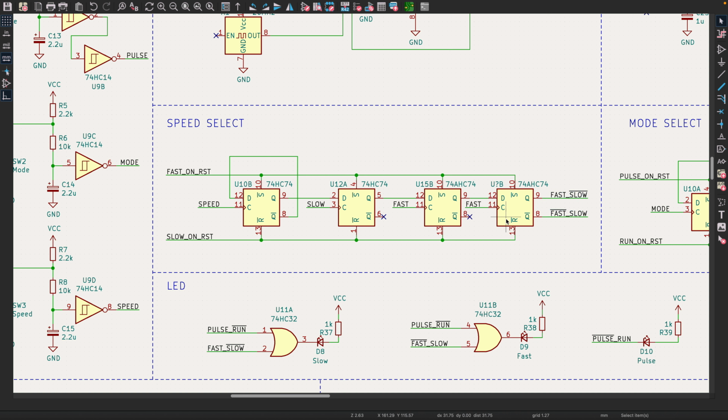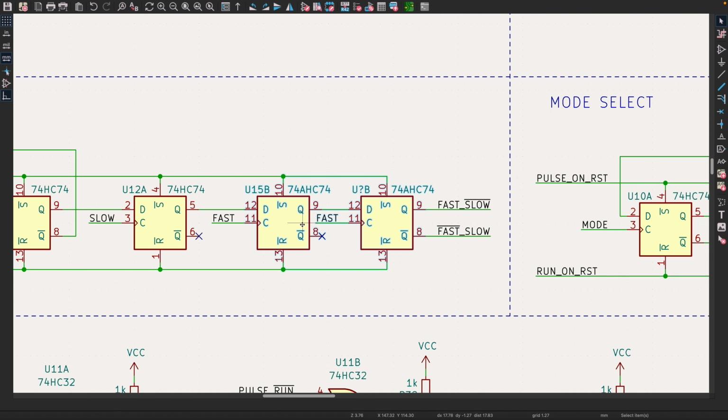So this is the new circuit. Now, if there is metastability at the output of this flip-flop, or this flip-flop, or this flip-flop, because we have two flip-flops triggered by the fast clock rising edge here, the signal will have some time to stabilize, and that's going to be the interval between two rising edges of the fast clock. And that's generally enough.